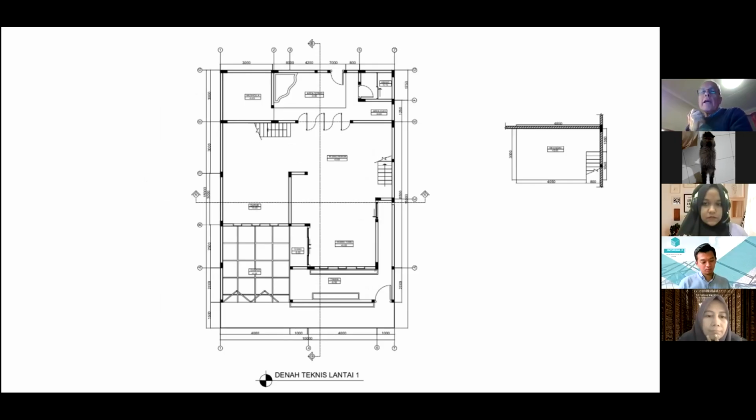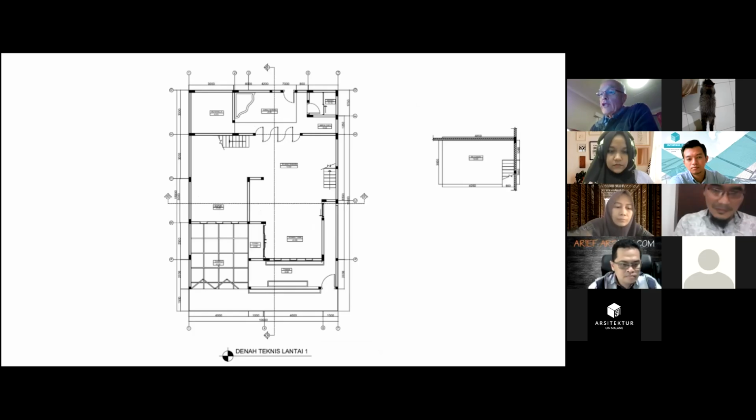Now, when it comes to reviewing the structure of a building, I personally suggest doing it in two steps. First of all, look at the gravity loads on the building and see if the structure is adequate for gravity loads. And then we move on to the horizontal forces on the building, mainly from earthquake. And so that's the approach I'm going to take with this building.